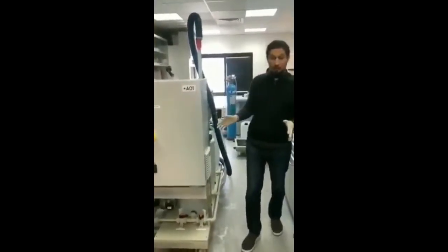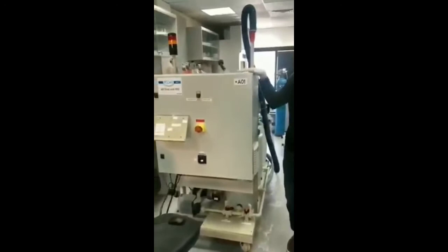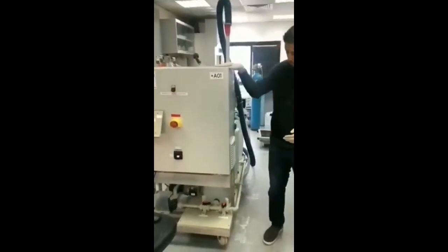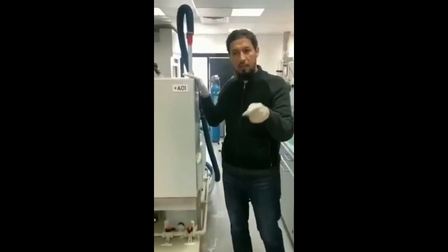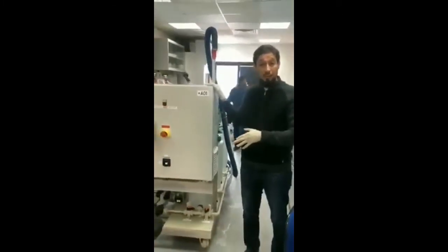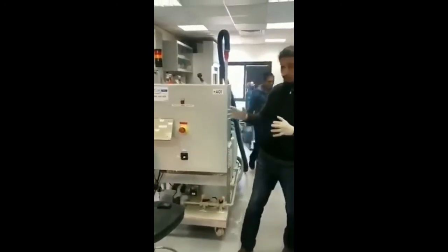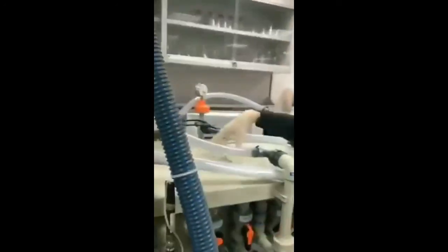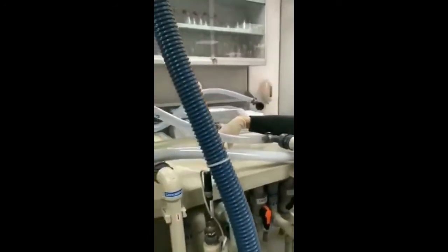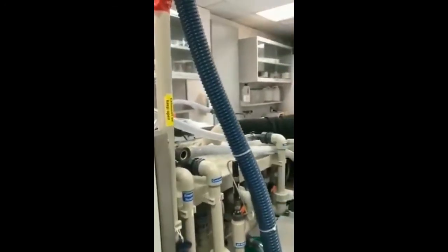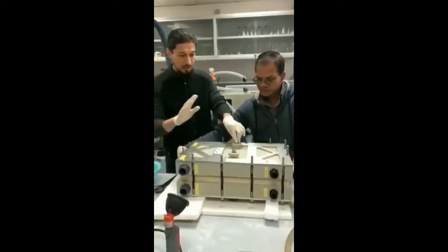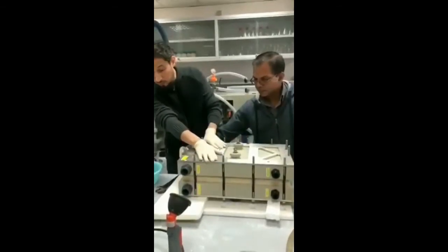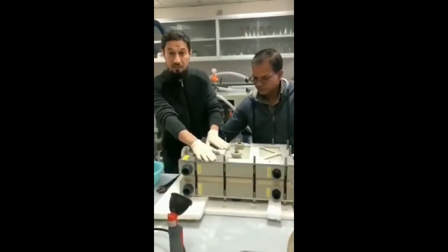The ED pilot plant, which is a big one, costs maybe $30,000. And this is what we actually use to convert the brine into edible salt. The one we just opened was on top here. So we removed it for maintenance to change whatever fouled membranes and put them back. The electricity goes into the system. And then this is the top part of the membrane stack. This is the ED membrane.